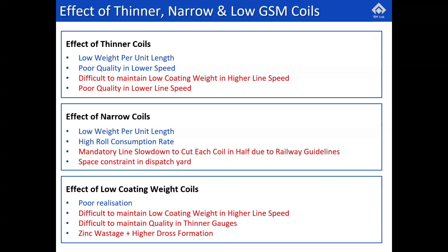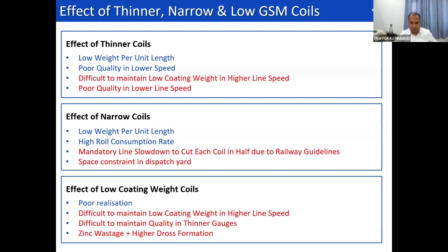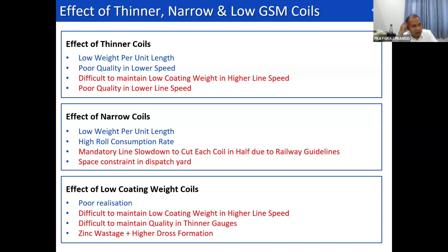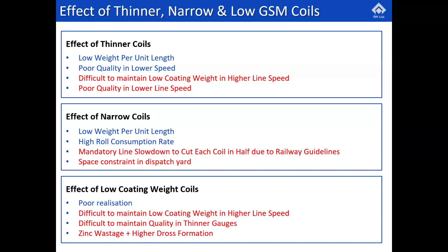And with the pot's chemistry that we maintain, it is very difficult to have bottom dross. And for top dross, if the pot's dross level is maintained, it should be similar behavior for thinner as well as thicker coils. So I am understanding the point you are trying to make. The customers complain of it as a dross carryover, rather it is due to turbulent air pressure of the air knife. It is a rough coating, sir, due to some interruptions during the continuous production process. If there is an abrupt line slowdown, this slowdown part goes as rough coating.